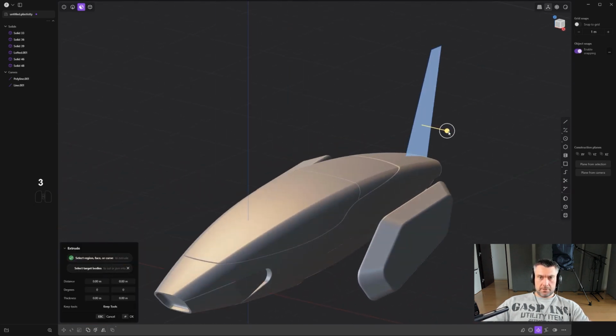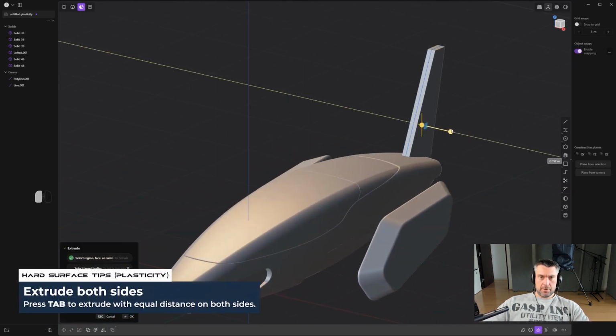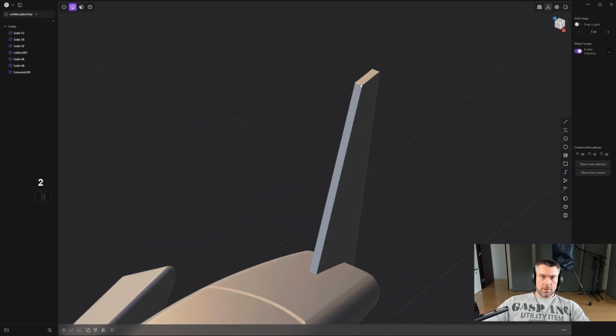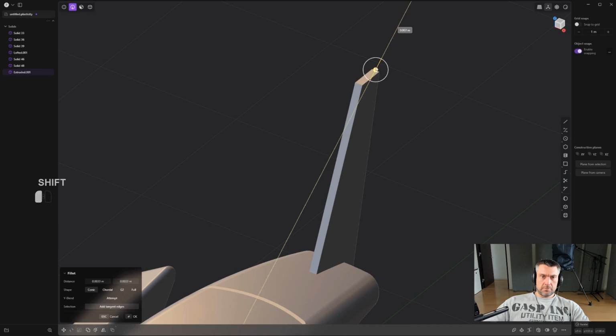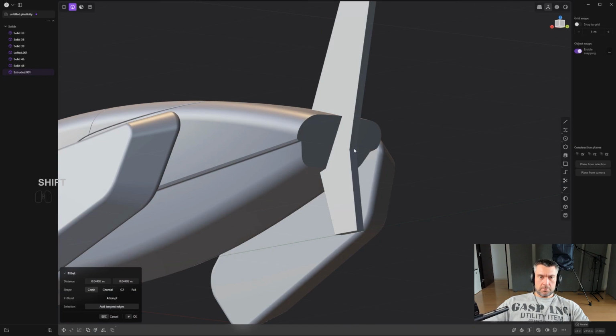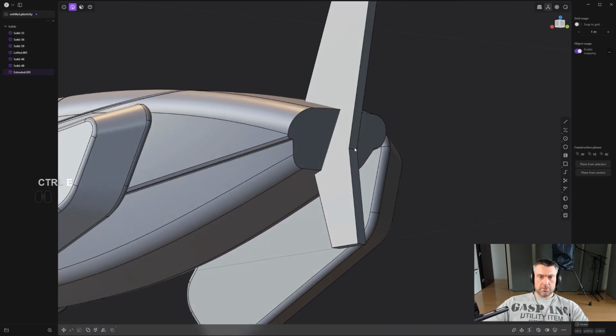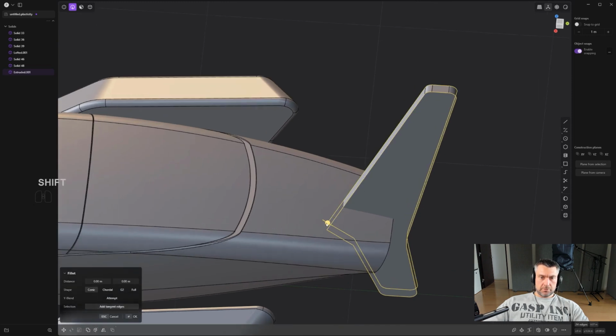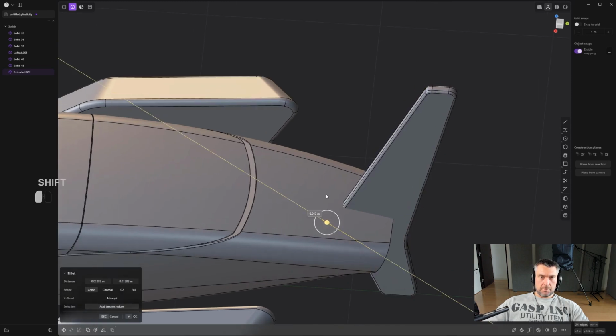Select that, and we're going to move this and press Tab. So you're going to move on both sides. Don't make it too, too thick. It needs to be kind of thinnish. These two curves, we don't need them. We can nuke them. And we're going to bevel these, okay, to the softer. And we're going to bevel this one. So let me just press Ctrl E, I can't see. Bevel this one here, and we're going to bevel these two. All right, let's bevel these.